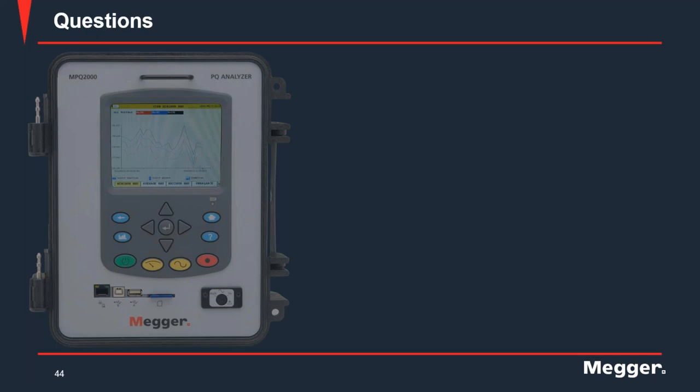What will happen is the MPQ won't start running the test until 10:10 a.m., and then you get your first set of values at 10:20 a.m. So all your RMS data points will be at 10:20, 10:30, 10:40, and so on. That gives you a certain standard format as far as data timestamps are concerned, and that helps with synchronizing with other systems or with data files from multiple recorders.